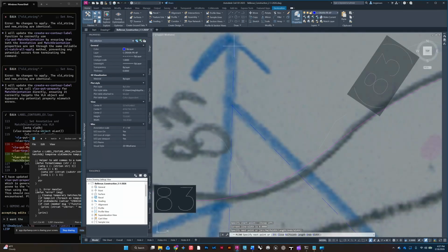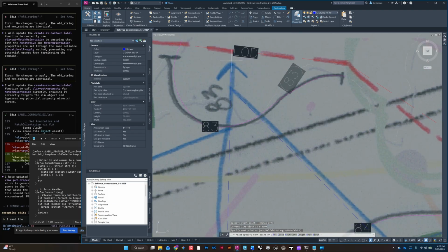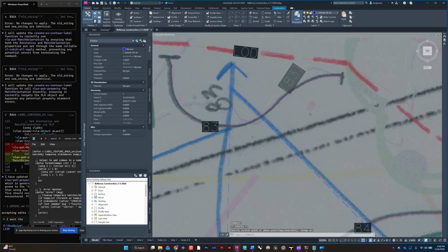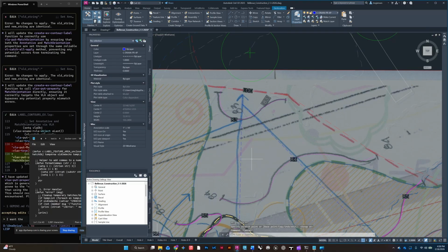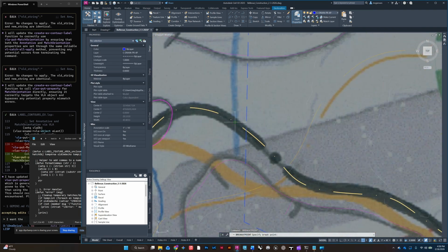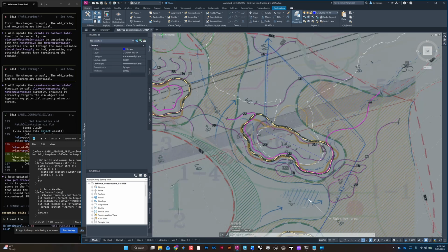We could try to just line it up, but again, AutoCAD is precise. So we're going to go out to here, and then we're just going to take this other line with the endpoint and move it with our object snaps and snap it to that line so that we can be precise. Yet again, we want to do break at a point, and we're going to break it right at this intersection where it is no longer bunker, and this is solid pipe.